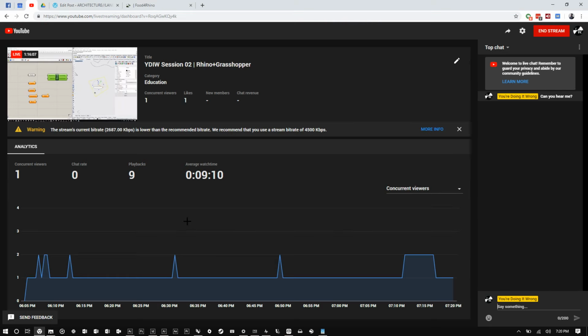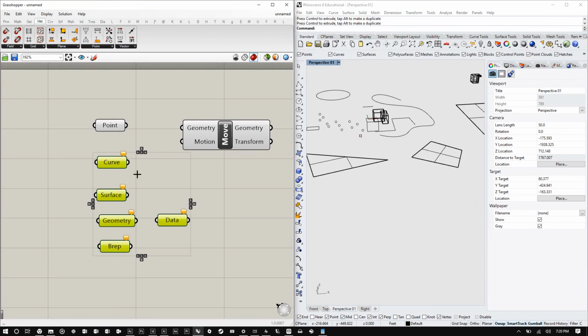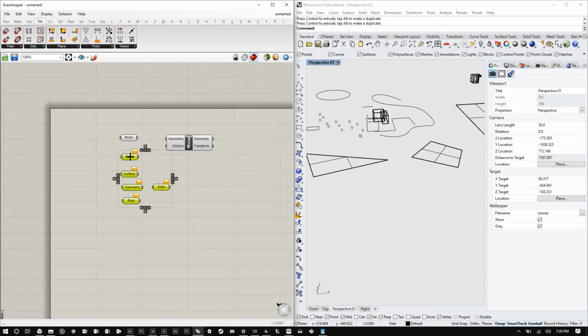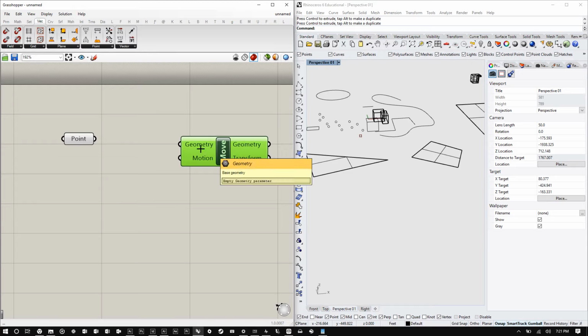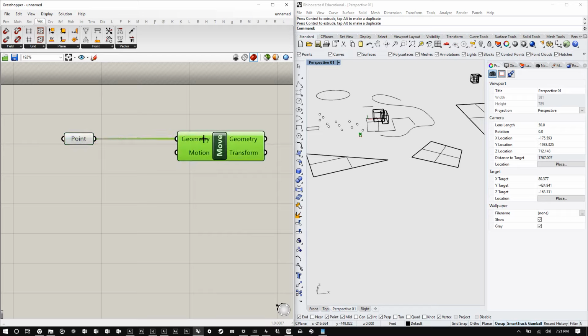So within Grasshopper, I'm going to move these guys out of the side. So now I have my command, and I have my what. So I have what and how. Now I need to tell Grasshopper by how much and in which direction. In Grasshopper, to connect two nodes together, you click and drag, and then you place it and let go. And that will connect two components together.